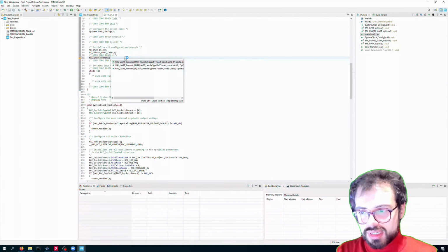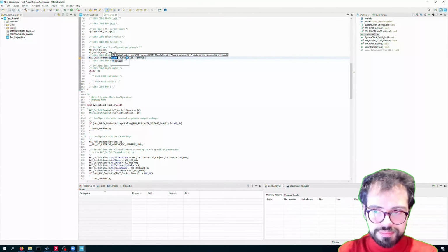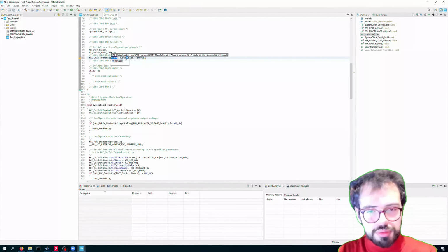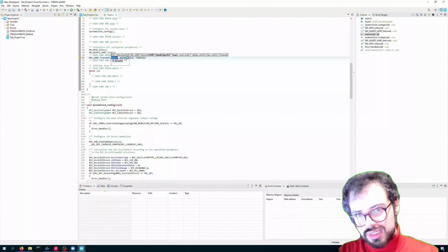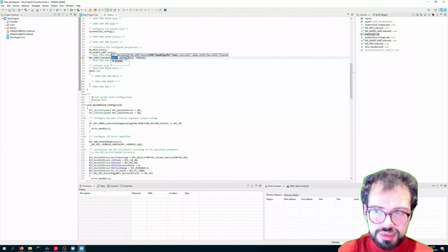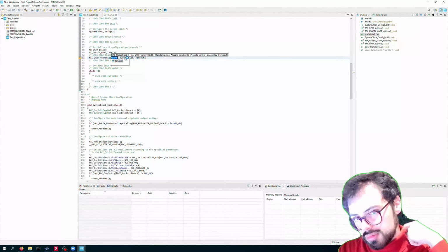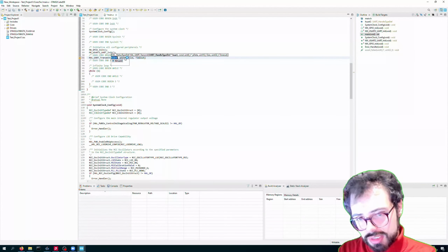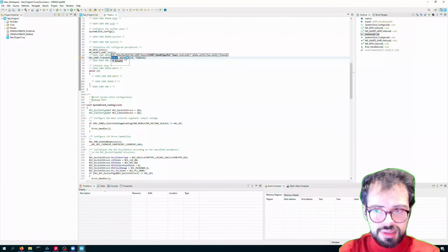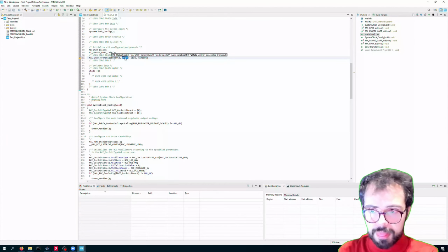You can say that the function we want is the first one, Uart transmit. The other ones, we will probably see the Uart IT later. Without probably, we will. But for this example, I won't show this one. In this case, we can directly choose the pointer. Here it wants a pointer, you can see the star here. It wants a pointer to the structure that is used to describe the Uart2. So you just put &huart2.